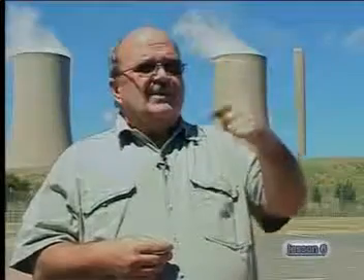It eventually links into substations. Now, substations, again, the opposite happens to what happened at the power station. At the power station, we step voltage up. At the substation, we use transformers to step it down. We step the voltage down to voltage required by a specific user. Say, for instance, it's a nearby town. So we step down from 275,000 volt to 88,000 volt.